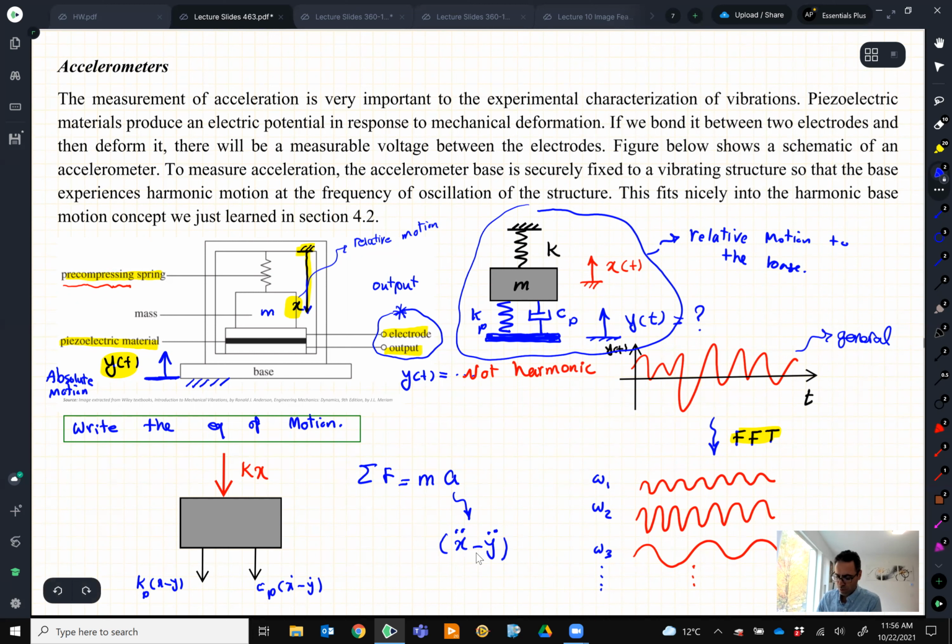So you do your test, and since it is vibration, you will get a value for x, maybe a graph of something. This graph is over time. The y-axis is not acceleration, it's voltage. Like any accelerometer that you purchase, the output is a voltage, okay?